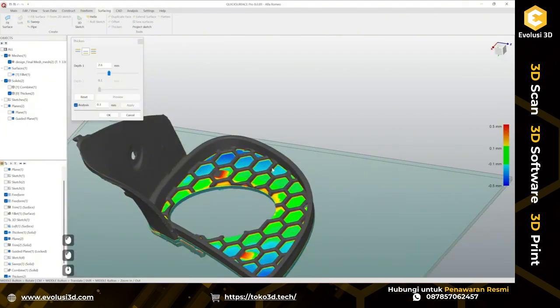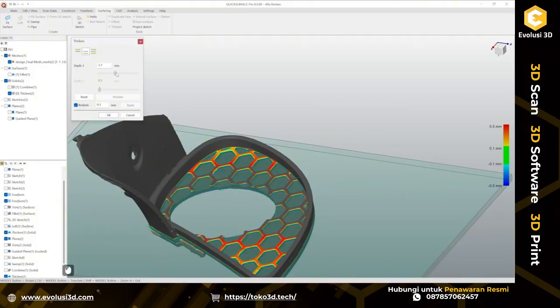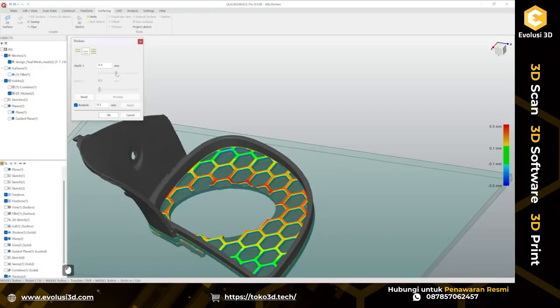After that we can create another cross section sketch and extrude it further, just this mesh grill here. Or we can go higher up, say for example like this, to create one super thick part, then create a cross section and create solid bodies that we will use as cutters here.